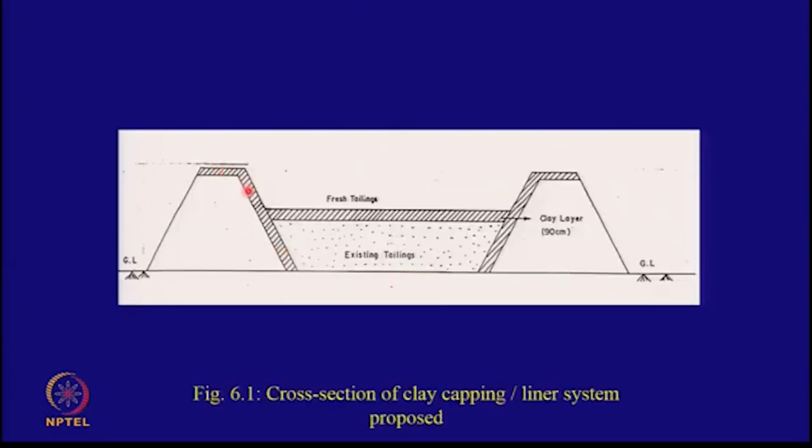One of the consultants gave the solution that all right, now this is hazardous, so let's cap it and then let us fill the ballast tailings on top. This will work as a cover and a liner for the new tailings, and nothing will go through. But the problem was, with time these tailings which are hydraulically deposited will settle, and this will all have seepage paths and it would not work.